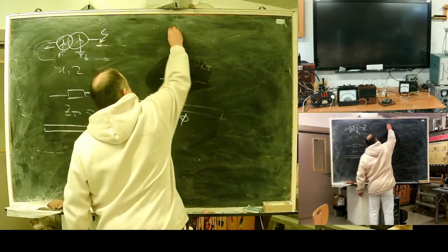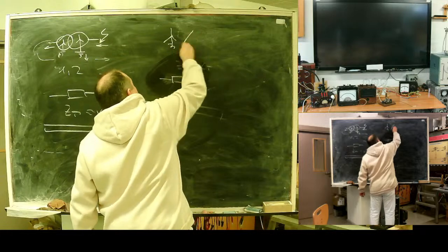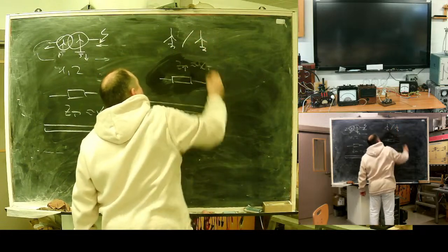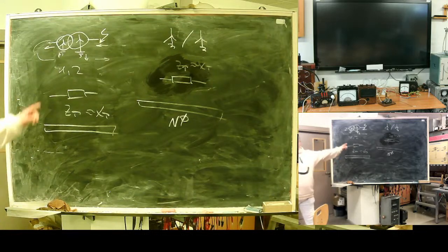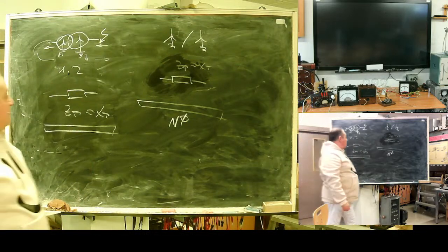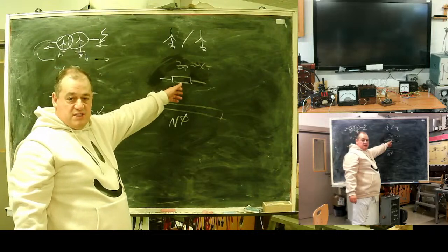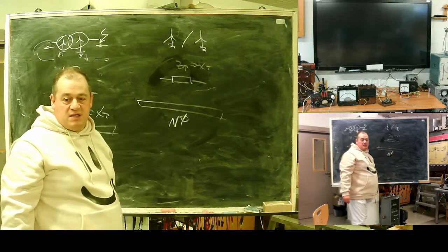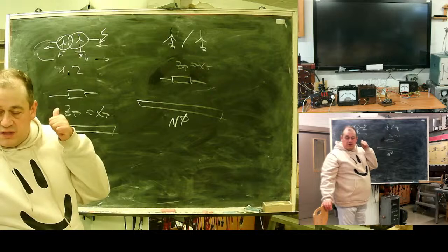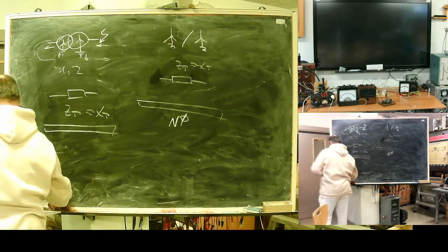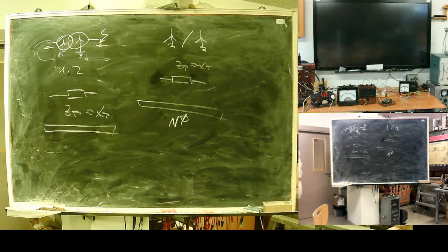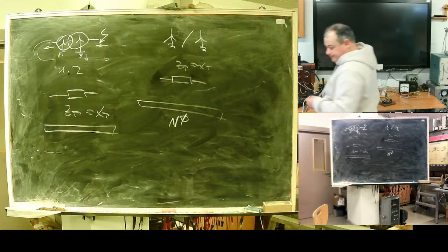For the case of delta grounded, zero sequence will be transformed forward. And our transformer in the zero sequence circuit will appear with Z transformer reactance found from the short circuit experiment or test.